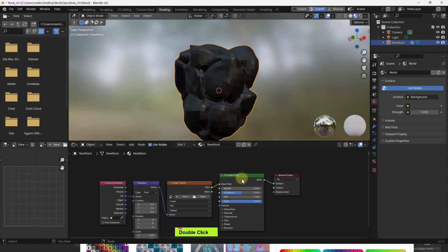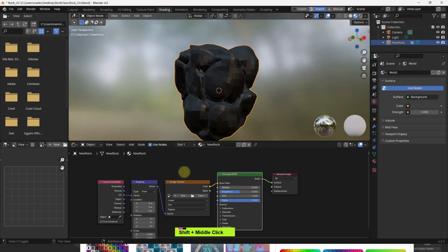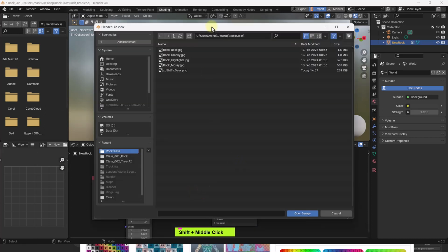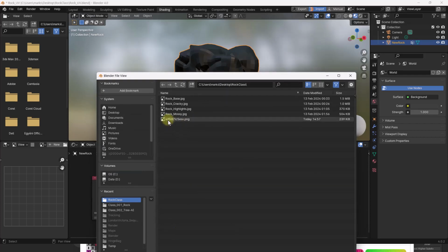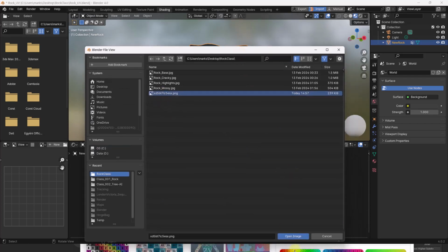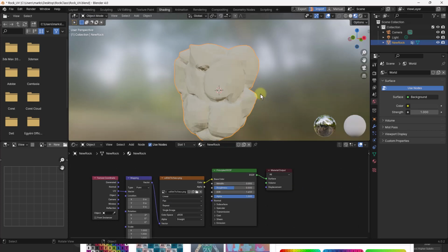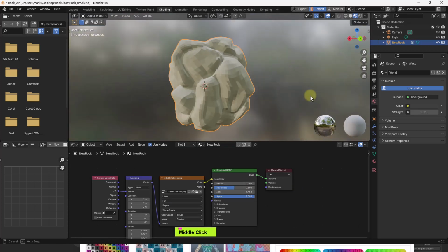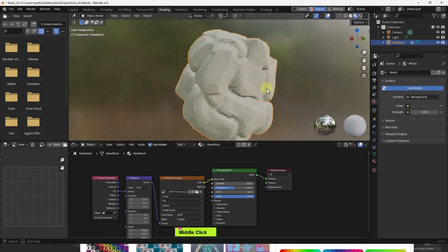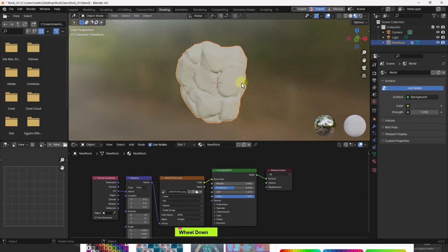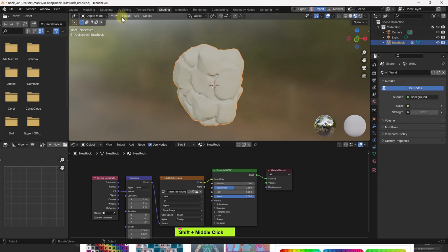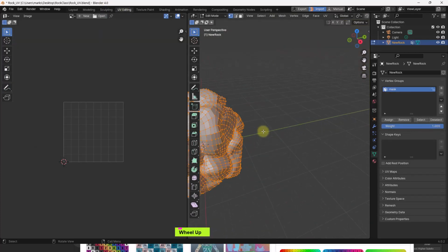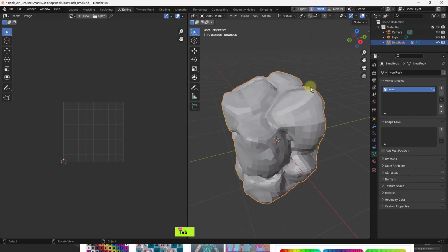When you have selected the material and you press Ctrl+T, it will set up a texture channel with all the nodes. So I can open this, whatever name it is. As you see, there's not really anything in it because the texture information is just not there yet. So let me go to UV Editing, and we are in edit mode.